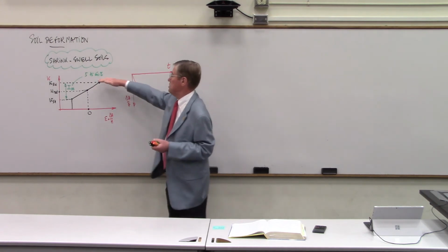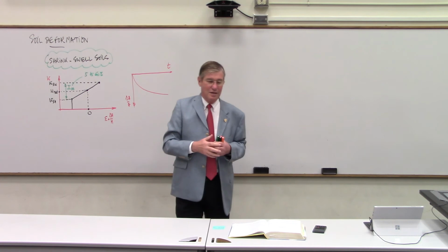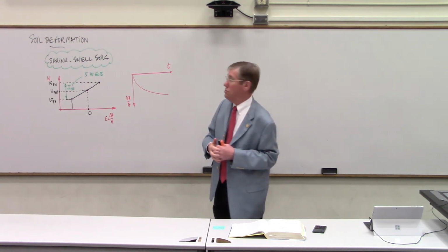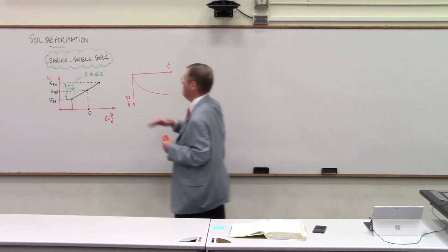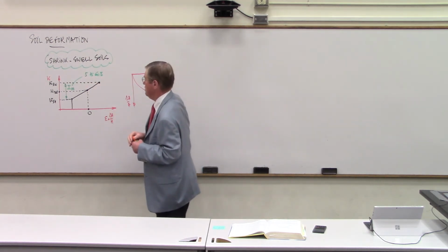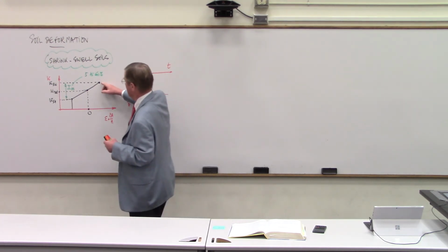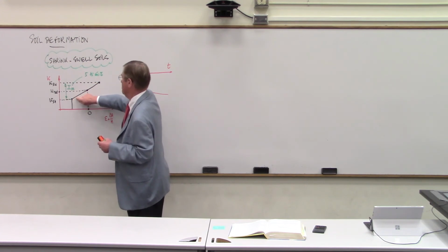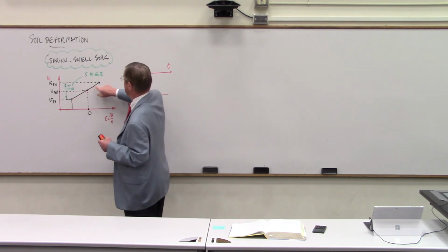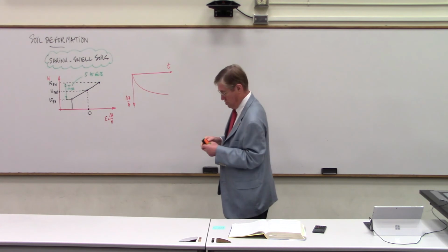And if you find yourself at 60%, you're in bad shape, because that's a very shrinking, swelling soil, and you have to be very careful with foundations that you place on them. If you're at 5%, it's not that big a deal, and you probably can live with it. So in other words, that line can reduce in length here. You can go up like this if you have a silt, a relatively clean silt and not very active. But if you're at 60%, then it's big trouble.